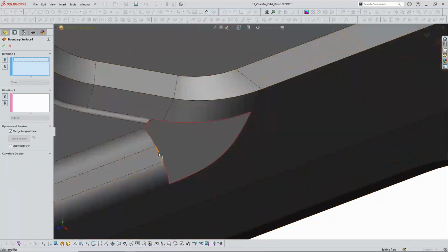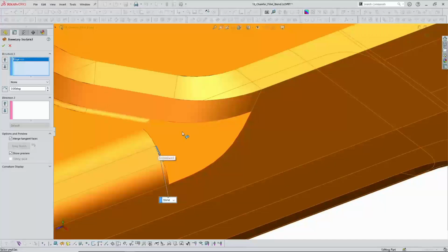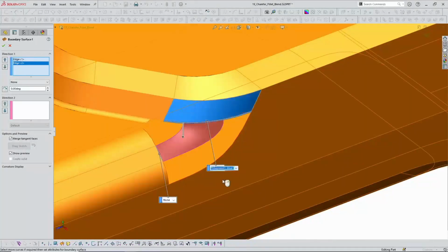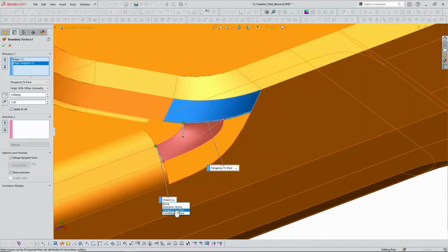So going back through this example, I'm going to blend from this edge into this edge, and by default, the surface or the boundary is larger than I want it to be, but I can grab these little connectors, I can pull them back, I can change my tangency, I can change my tangency length, perhaps I would want to explore 1.2 on these, so I can sculpt what this transition is looking like.